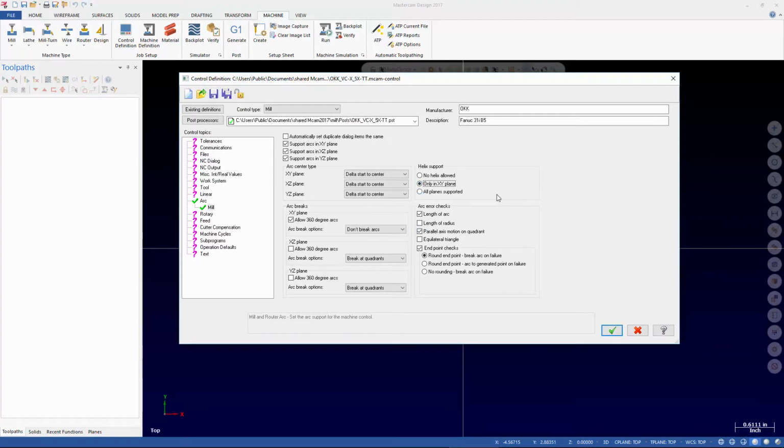Really, what other tool besides a right angle head are you going to do helical motion with in the XZ or YZ plane? It's just one of those things that rarely comes up. I guess on a head. Yeah, for the table, all of the cutting really takes place in XY anyway, since we're just positioning the table and then moving the tool in to do the cut.